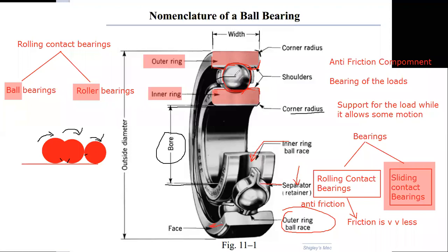Actually, generally, you would have seen that these types of bearings are sealed. If you pick up a bearing, you would see that both of these sides have a plate that seals it, because first of all a lubricant is put in there, and then they are sealed so that they are not opened again, and nothing from outside, no foreign particles, enters these grooves and blocks the way of these balls.